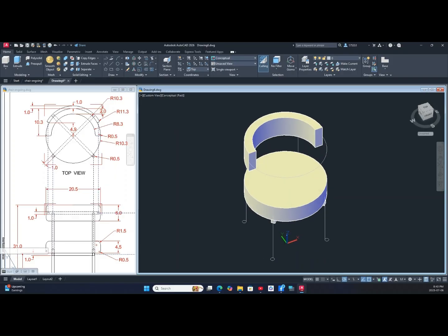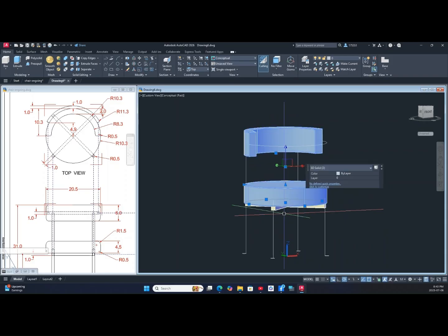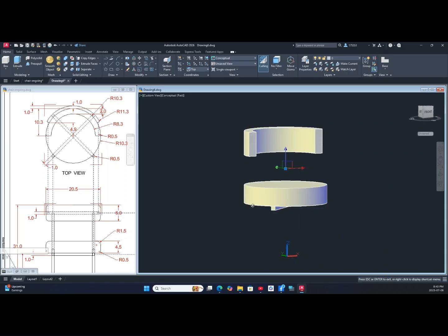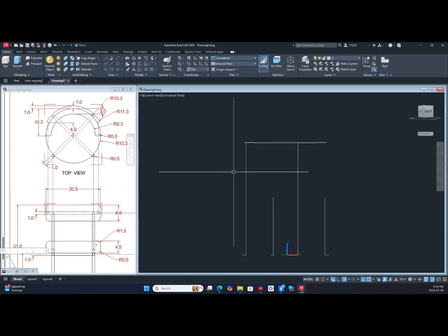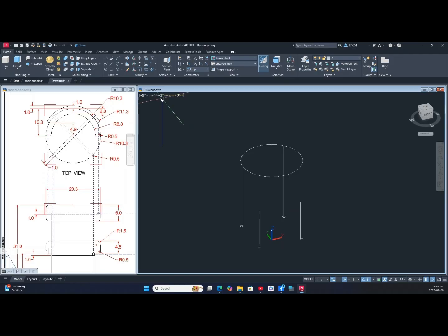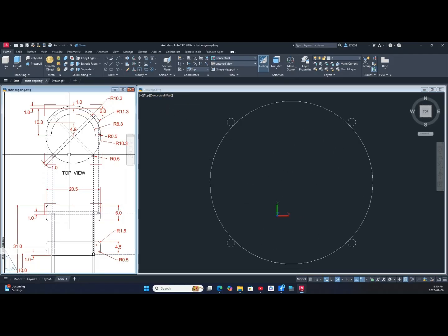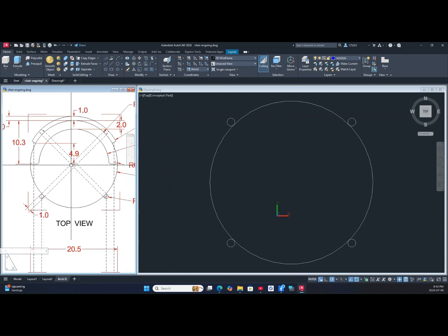And I'm gonna create an arc. So again, I'm gonna hide these extruded objects. Right click, hover over isolate and select hide objects. Now I'm gonna bring this to top view and cut this circle. So the arc, the cutting point is 4.9 from the center of the circle. See this one? I'm gonna draw a line, a guide from center up to this point for 4.9.